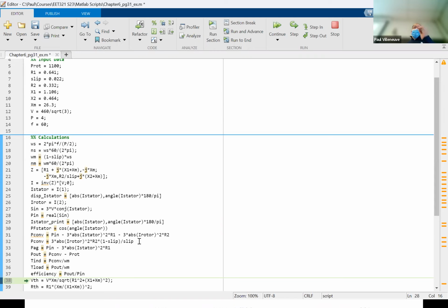Well, it's a great point. It's when to use what. Everything in here is entering your data in your calculator, right? P rotational, all these would be writing it on a piece of paper and then putting those variable names. Once you get to here is when you do the calculations. That's the power of MATLAB. I put all my variables in here and it calculates it for me. You have to do that on your calculator, but these steps right here, these are calculator steps. And to solve for this impedance network, you could either do the series parallel combinations, or you can just use KVL and loop equations, and you can pull that value out.